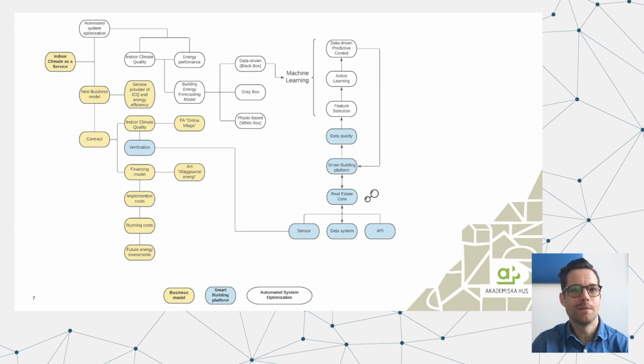Data from the building automation system and the demand control system are extracted according to the configuration specified in the RealEstateCore tag list, using an IoT Edge module running on the IoT Edge device physically located in the building. The building automation system and the demand control system communicate by Modbus TCP, and data are translated using IoT Edge modules. The module function is to pull the source system according to the configuration specified in the RealEstateCore tag list. The REC tag list differentiates between a sensor that represents a read operation and an actuator that enables the writing of values back to the Modbus register and further back to the building system.